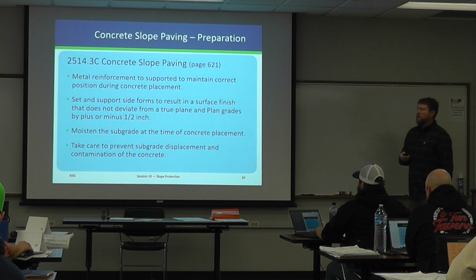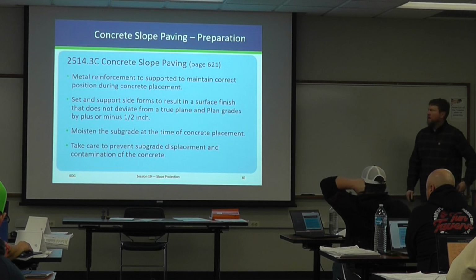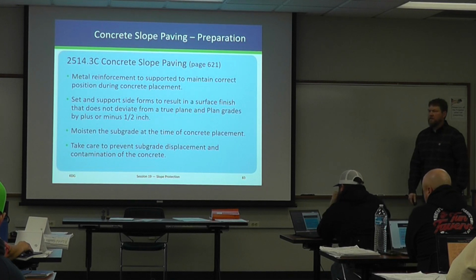It's reinforced concrete, so we want to make sure that reinforcement's in the correct position prior to concrete placement. Obviously, you've got formwork on the side. Try to make sure that's as close to plan as we can.